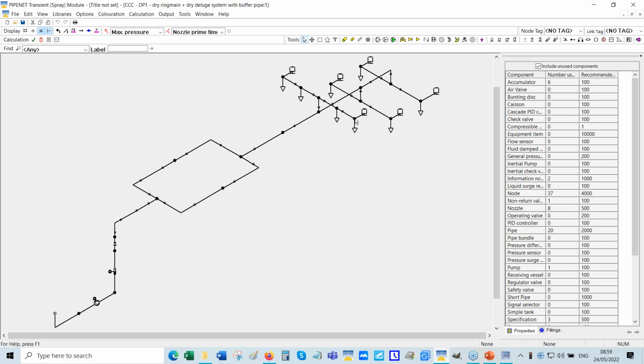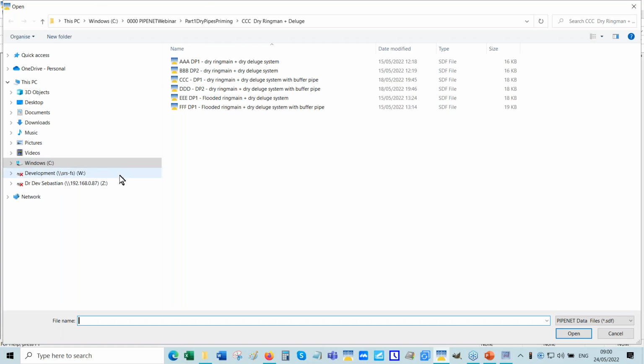And this is a very effective way of mitigating pressure surges which arise when the deluge system gets primed, at the end of the priming of the deluge system, because you can get some high pressure surges. It's a very simple solution. All you do is to extend the pipe and put a blank flange. As simple as that. Okay. Let's go on to, as I say, if there's time, I'll come back to that.